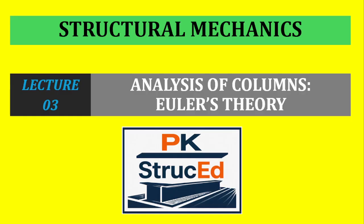In today's lecture, we move from trusses to another very important structural element called columns. Columns are vertical compression members which are used in buildings, bridges, towers, or even industrial structures. While beams fail mainly due to bending, columns fail primarily due to buckling instability. Today we'll study Euler's theory of columns, which explains the behavior of long, slender columns under axial load.